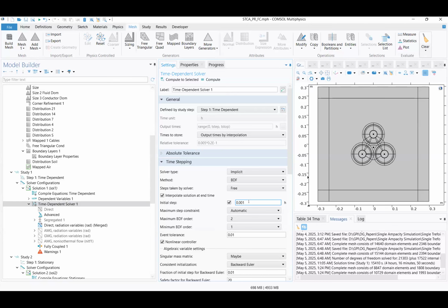for in my case heat transfer, there's something called the time constant, right? Or even the electrical circuit time constant, right? So you have an idea of what the time constant is, you want your time step to be much smaller than that time constant, right? So at least by 100, maybe by 100 or 1,000, but you want to have a reference. You can't just use any time step, right? You have a reference with a time constant or period, and that's how you proceed.